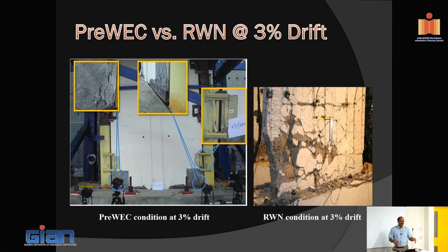So this is where the resilient design concept came about, right? You make the structure more resilient. If you have a building with both walls, one on one building and one on the other, if you look at the one on the right, even a good structural engineer will be hesitant to go inside. Whereas the one on the left, you can inspect and evaluate it, because you don't want to have no damage but still be in a bad shape. Those things we can easily evaluate. We can look at the post-tensioning anchorage and things like that to make sure that the system is still intact.